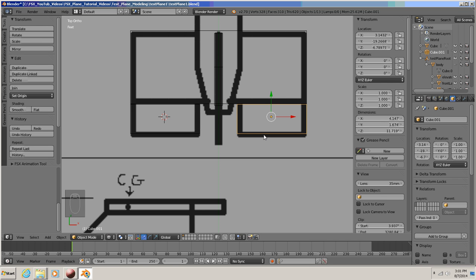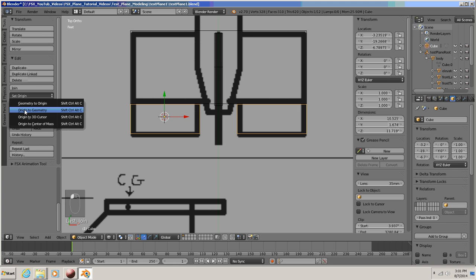Okay, we've just duplicated. Now what we're going to do, we're going to hold down the Shift key. We're going to select the other elevator control surface again. So now we have them both selected. We're going to go over to our left toolbar, and in the edit, you'll see there is a join. Click join. This basically combines these two objects into one object. Next, we're going to move our center location for the object in the middle. So we're going to hit Set Origin to Geometry.